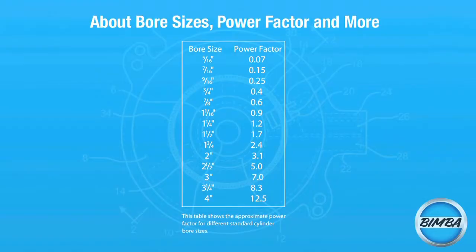Ideally, the cylinder should be able to move the minimum load at the minimum acceptable velocity and the application is a little different and other factors may apply. It's always wise to make your cylinder size selection with the expert assistance of your cylinder manufacturer or distributor.